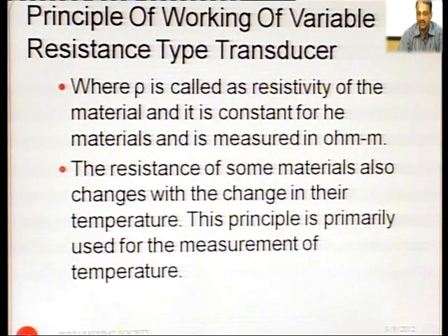The resistance of some materials also changes with the change in their temperature. Apart from these three values, rho, L or A, there is another parameter upon which the value of resistance depends, that is the temperature. This principle, that is change of resistance with temperature, is primarily used for the measurement of temperature. So, this property can be used to measure the temperature.